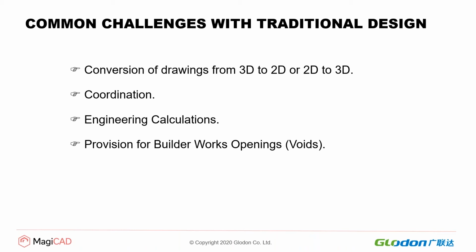And we also have pipe sleeves. Some areas, like where we have crossings through beams and all, we also need to put the pipe sleeves. All these things in the traditional practices were a bit difficult. Even if you are using any other BIM workflow, it is also carried out as heavy work, with a person especially assigned just to carry out these provisions for building works, which can be done in a faster way.